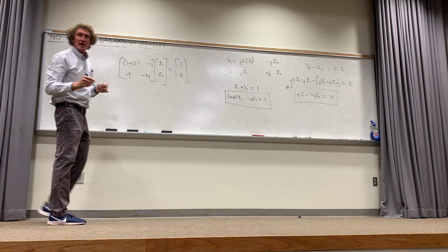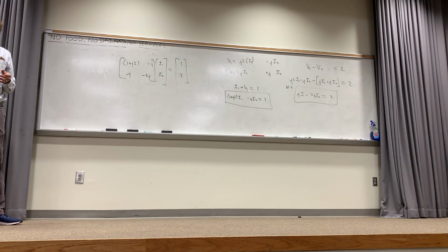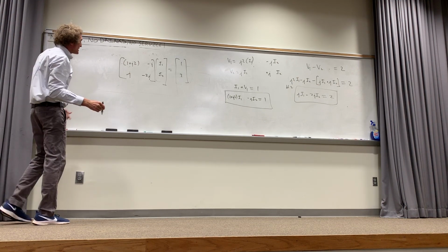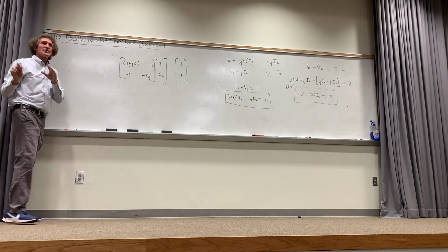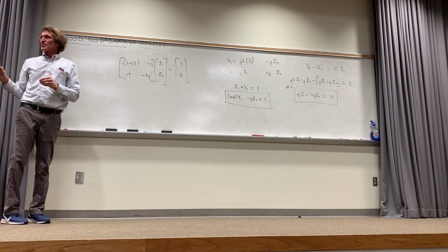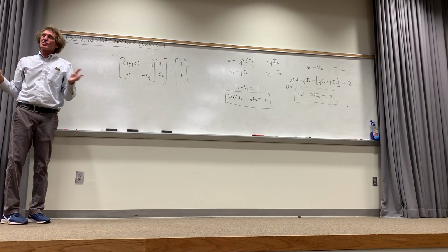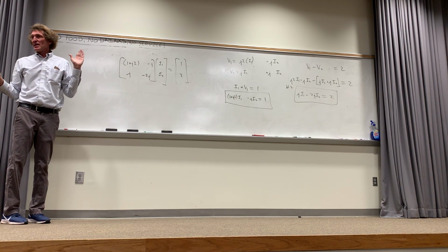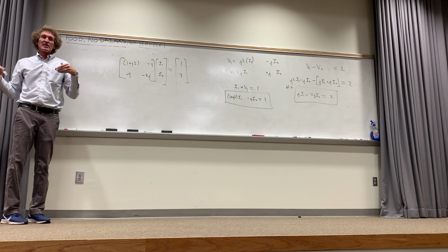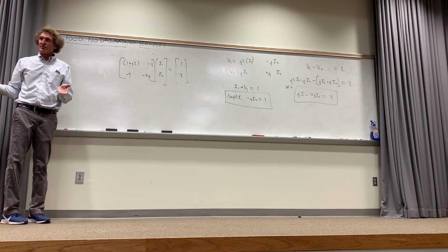Y'all agree with that? Now that I have that, I'm going to solve for I2. I don't care about I1, I care about I2. Your calculators can do this directly, can't they? But really, what you need is the determinant of this, first by itself. Actually, do it on your calculators. I'm not going to do Cramer's rule here. I can do it with Cramer's rule, and the solution manually does it with Cramer's rule. I haven't used Cramer's rule, honestly, in any place but this course in the last 15 years. It's nice to teach you what your calculator's doing, but frankly, your calculators can do it a lot faster.